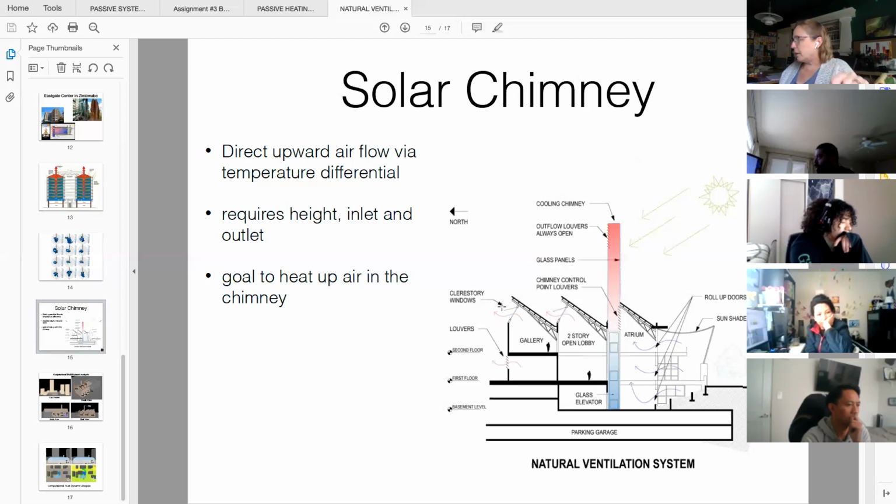Oh, and like many other sustainable projects like the Zion National Park building, we're combining multiple different techniques here. So the north-facing clerestory windows, which work really well with daylighting, also provided a pitched roof facing south that was ideal for an active solar system. So there's photovoltaic panels on the roof of the south-facing bays.